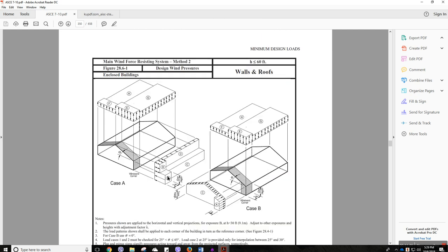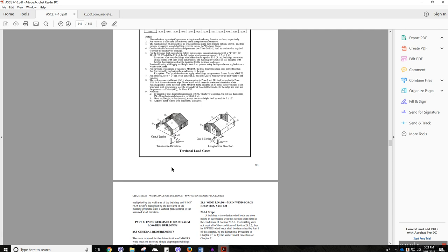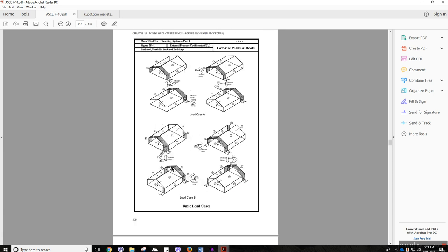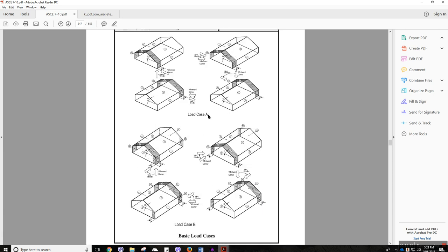For the height, we don't have any inclination, so the total height is going to be there. Another thing I just wanted to show here, a little bit up in ASCE 7-10, these are the 8 different cases that you need to apply the wind load. Keeping this one as 2A and A, B, C, D, and E, F, G, H again at the top, as we saw in the last one, and another one keeping that in 8 different directions.